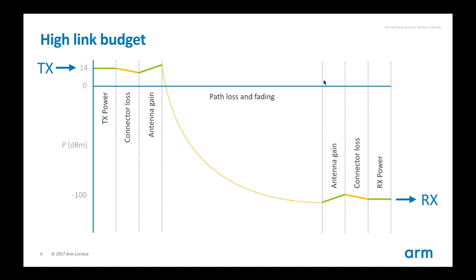An antenna, at least for LoRa, is very omnidirectional, but very often you don't want to send the same amount of power in every direction. The chance that your device or your gateway is in a horizontal plane is a lot larger than that it's right above you or right below you. So with the shape of the antenna, you can put a little bit more gain into the horizontal plane, so we win a little bit there.